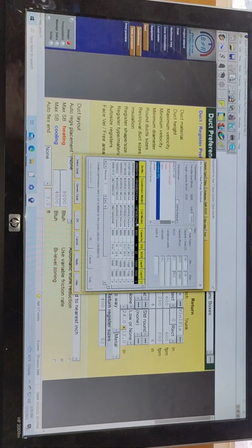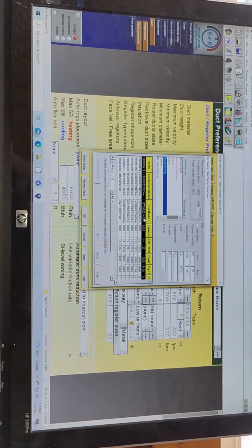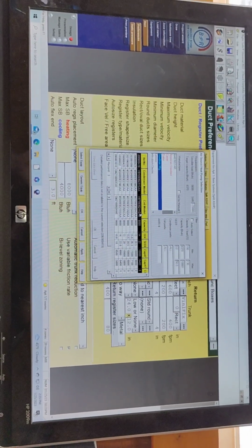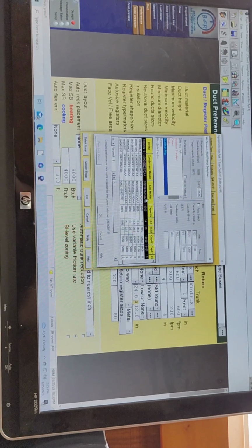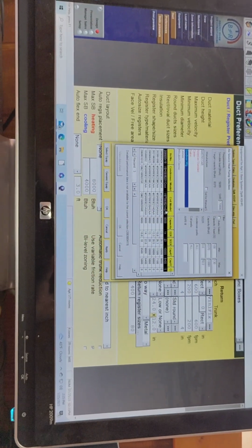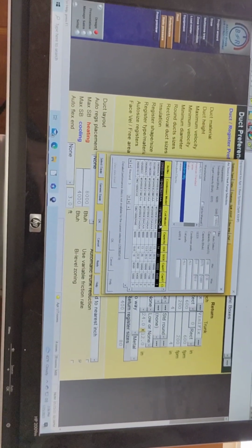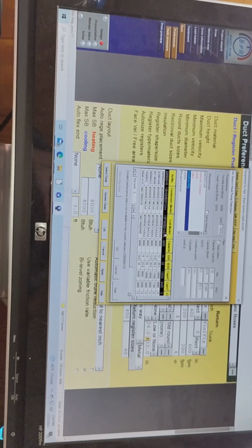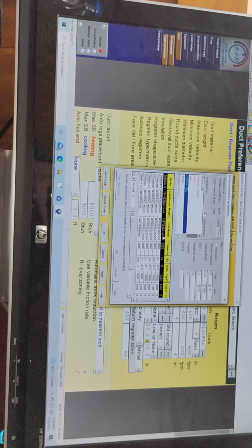If you go to a variable speed unit, they'll allow you all the way up to 140% of the load, because they know it can address the high end and even be more than what you need, so that if you have a 110-degree day, it can step up to there. But the important thing they're worried about as far as code and Manual S is that it's small enough to address humidity issues on the cooler days and your swing days.